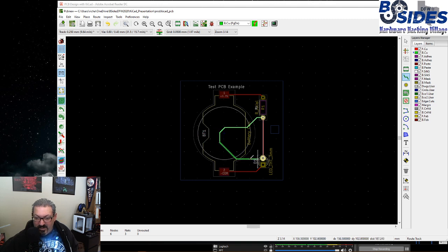And you can see when I go to connect it to this pin, it's removing my track on the upper layer of the board. So this is working with rules that say we are already connected here, so it removes this one. It decided it wants to put it on the back of the board instead.